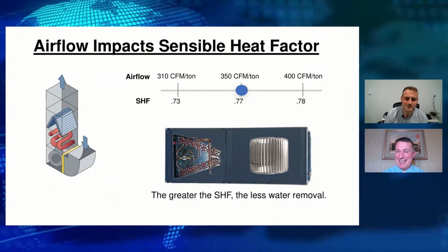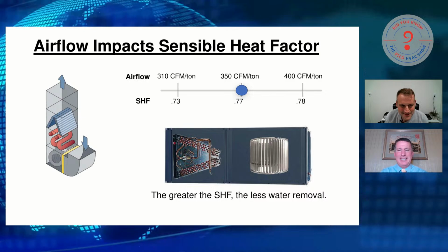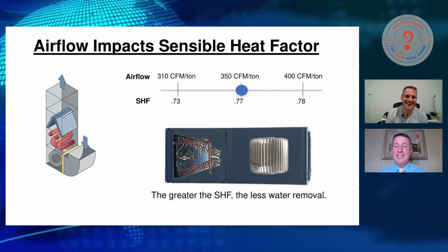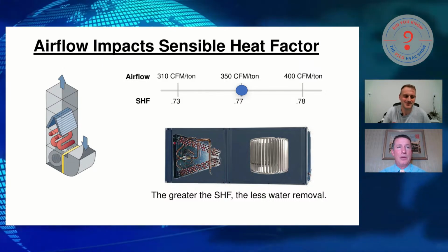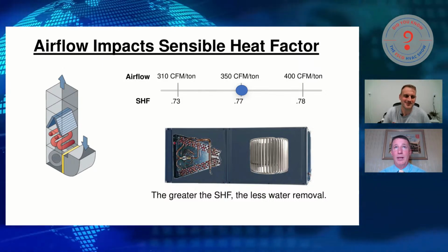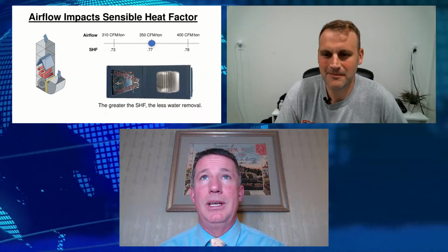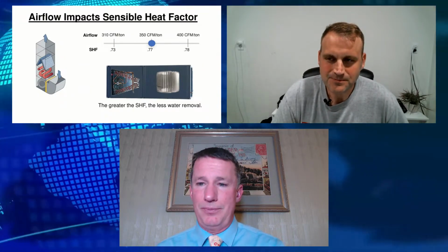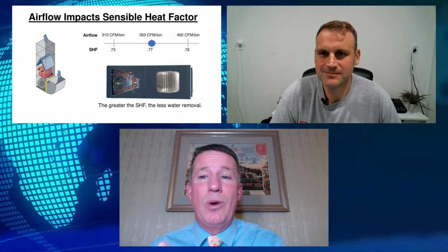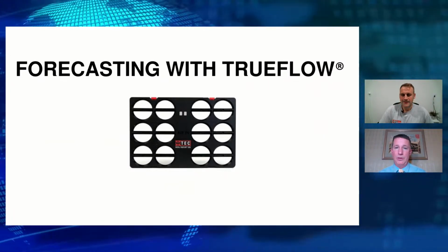Okay, fantastic. So, do you want to see what the future holds? Where do we go from here? When I was on the tech service side, I spent quite a few years doing dealer onboarding and site visits for tech support. When we start talking about new equipment, particularly modulating equipment like inverters, a lot of people don't understand the impact of static pressure, let alone on ECM motors. Now we're getting into variable capacity compressors and thermostatic expansion valve operation. We're getting into precision controls and operation.